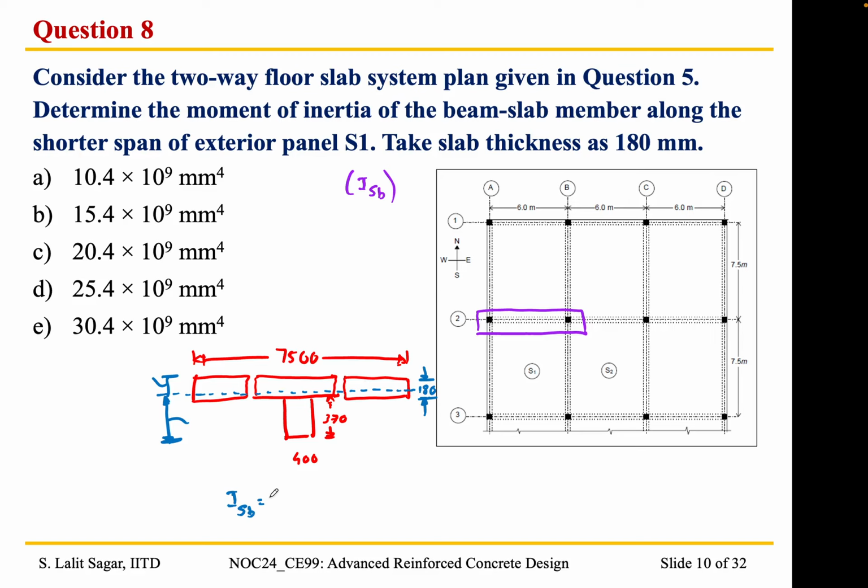So do we have an answer? Sir, 15.4. Okay, wonderful. That is the absolutely right answer. When I calculate the neutral axis, this particular distance from the top fiber, I obtained the value as 117.2 millimeter, and from the bottom, 550 minus 117.2, that is 432.8.